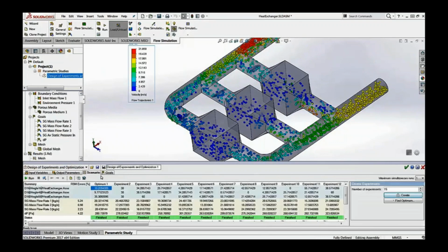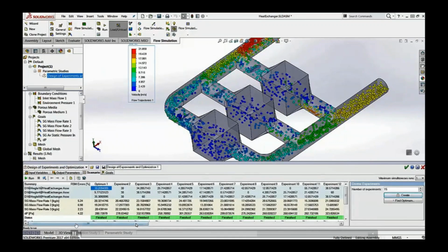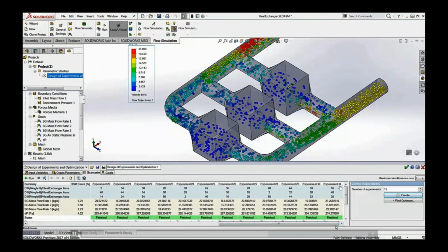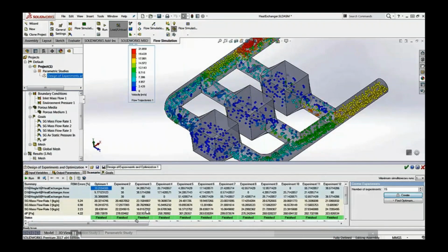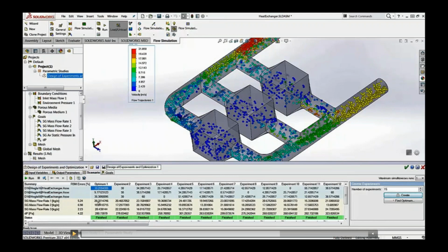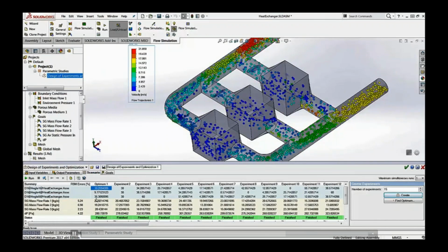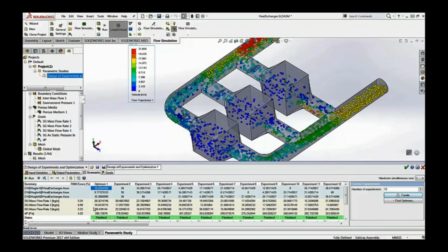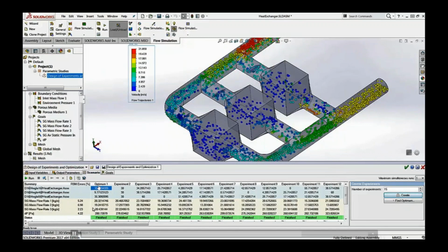So we have the scenario here, it's already run, and you can see that we have 31 experiments. Imagine exploring all the combinations of the valve angles from 0 to 60. Of course, it would take a lot more than 31 experiments. So basically, here is the beauty of the design of experiment approach. It's defining only what is needed, okay? And we have the optimum values.